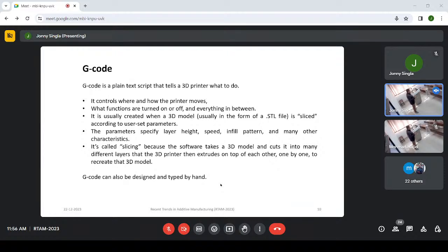If we want a very high surface finish, then we have to increase our speed. For different materials, we have different combinations, and it also depends upon the tool. In welding, there are again some parameters to be controlled: speed, current, voltage, depending on what you are welding and what your electrode is.